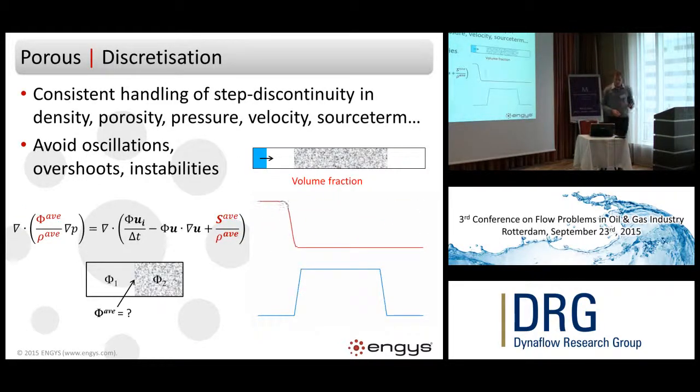And then, as I mentioned, the numerical handling of these kinds of discontinuities in multiphase flow becomes even more complicated when you have to cope with the arbitrary discontinuity in porosity, and therefore in velocity, which intersects with the discontinuity in density and therefore the gradient of pressure as well. So it's quite a delicate thing to formulate the equations in the right way that will allow, even in a simple 1D tube like this, all these different discontinuities to overlap on each other.